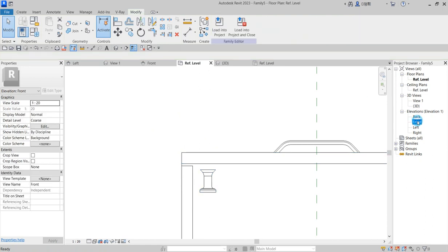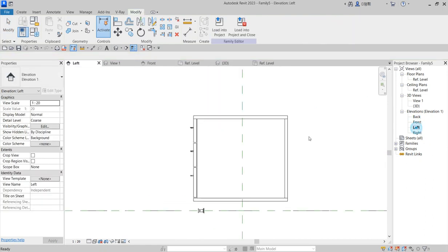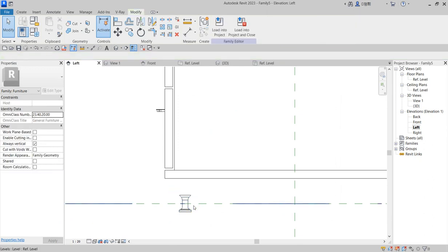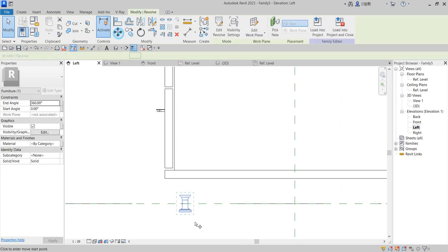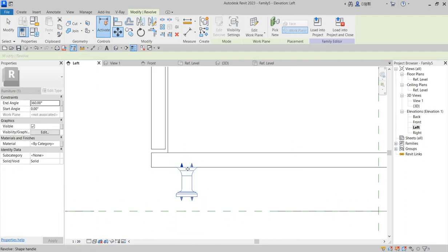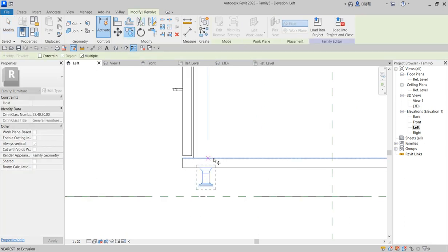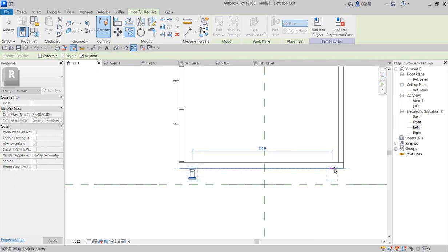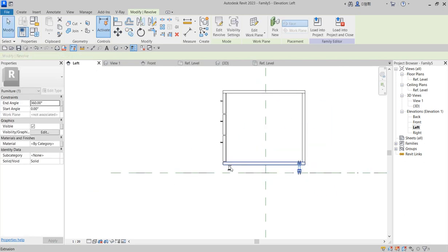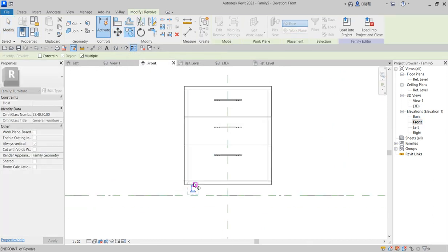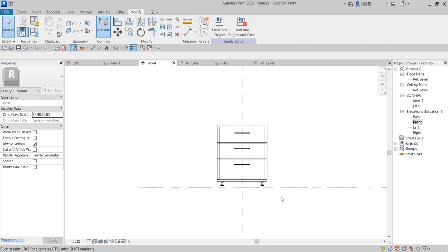As you have done it, you go to your left side. At the left side, rotate this particular one to 90 degrees. Good. Just delete the horizontal one. You pull this, you push it up. Good. So that is it. Now you connect this and say copy to this point. Select the two and go to the front elevation and say copy. You can even mirror if it's okay by you. Just mirror it.